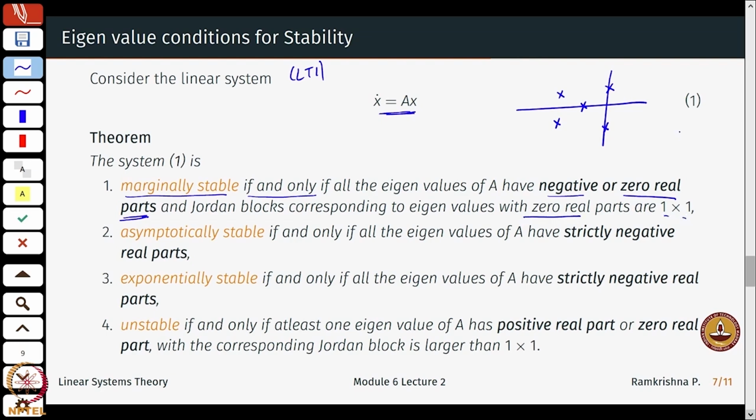So what does this mean? If I have poles of the form plus minus j, like repeated poles on the imaginary axis, this system turns out to be unstable. Okay, you can check for this condition. These are also covered in earlier basic undergrad control engineering lectures. Right? If there are repeated poles on the imaginary axis, then that leads to instability.